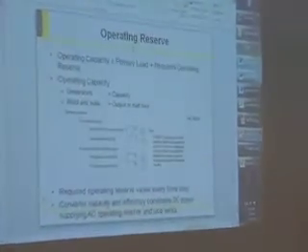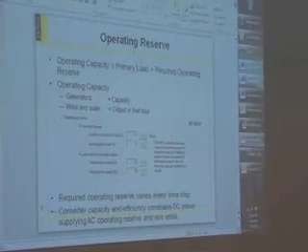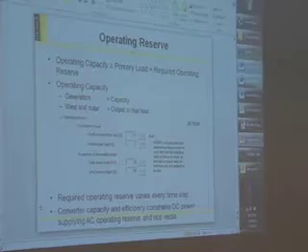But as the percentage of renewable output, that is not the nameplate of the renewable output. Again, that is going back and looking at the primary load. Let's say you have a 100 kW primary load, but you have 200 kW of installed capacity. Is that 100% of the 200 kW installed capacity, or is it 100% of the 100 kW primary? It's of the wind power output. So it's neither. It's what was the wind power doing in that hour.